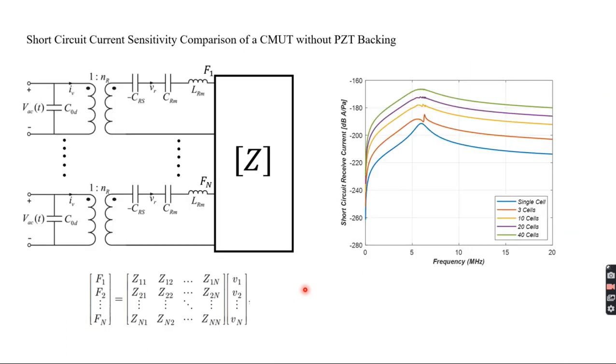Just to differentiate what happens once you introduce the low frequency stack to the pure CMUT elements. These are multiple CMUT cells placed together, connected electrically in parallel. So for example, you go on increasing the number of cells in one element from a single cell to, let's say, 40 cells. As you go on, of course, the loading is increasing, so it becomes very wideband.